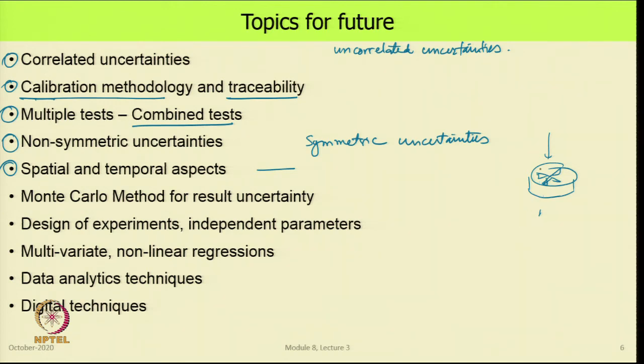This works fine if the velocity coming all over the anemometer is the same. If it is uniform over the face, this is a good instrument. But what if this velocity were larger, then this is smaller, this is even smaller, this is much smaller? Then what does the reading of the instrument mean?